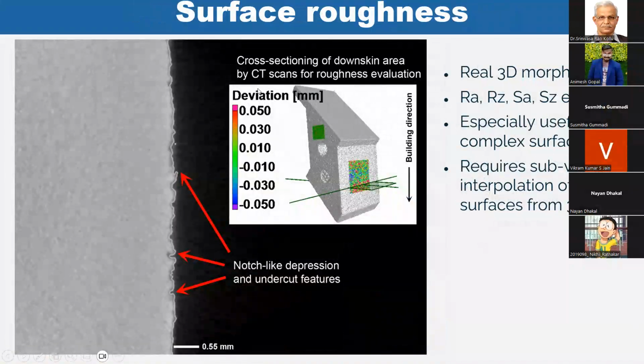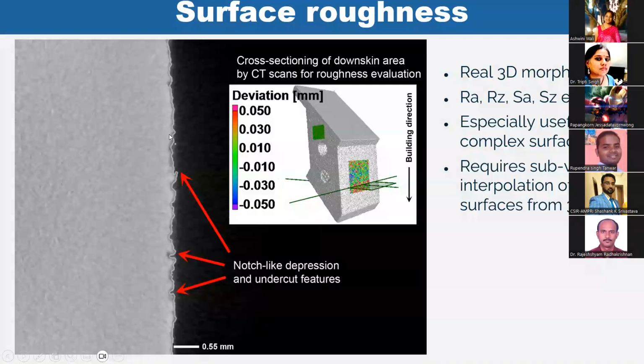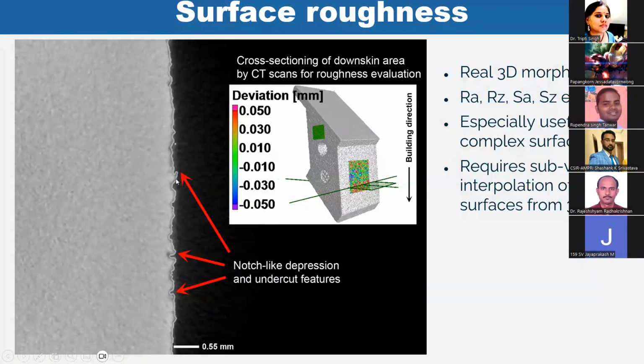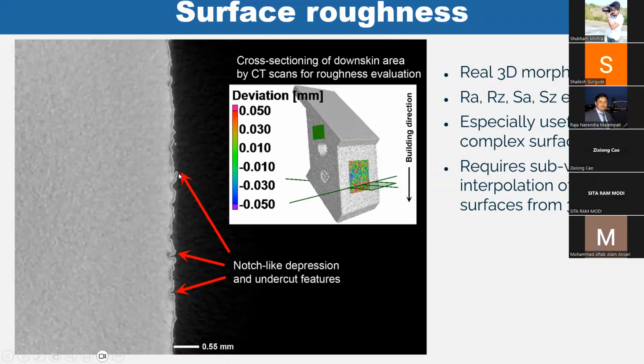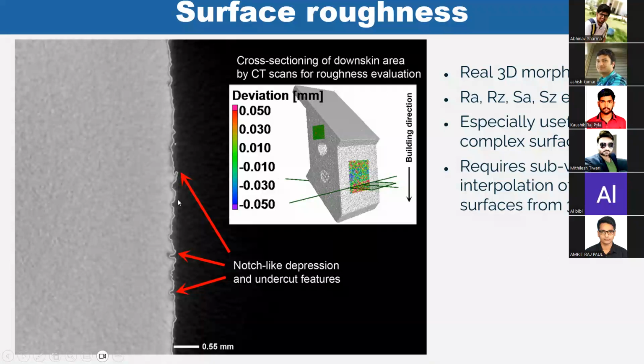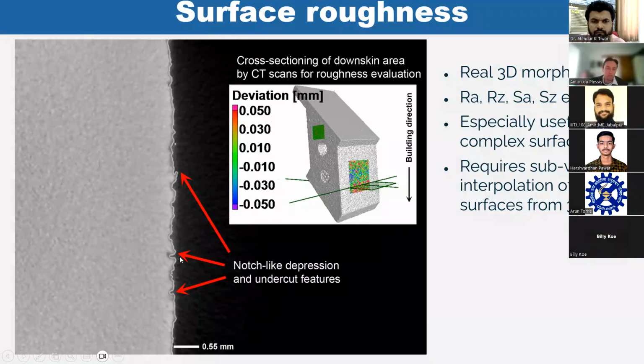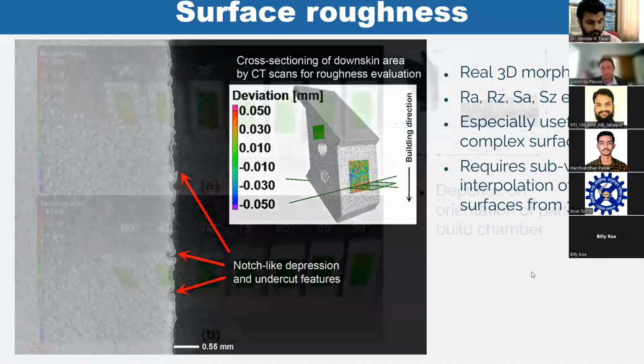This is an example of roughness, where the white line is the definition of the gradient, the midpoint between the material and air. And as you see there, there's an overhang that is visible, and also some surface penetration or notch-like depressions, which are important to understand.